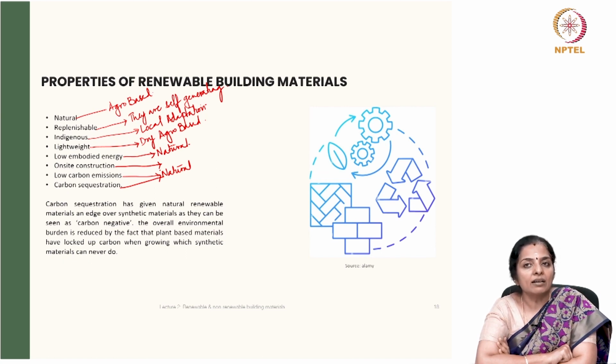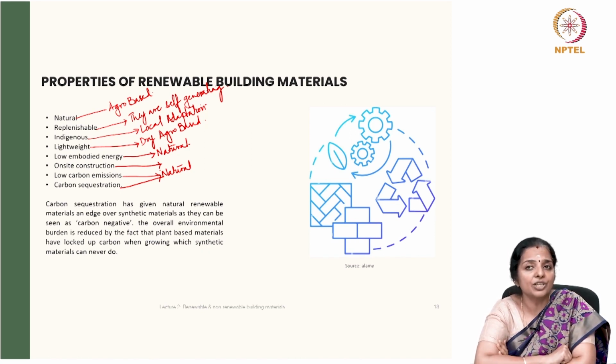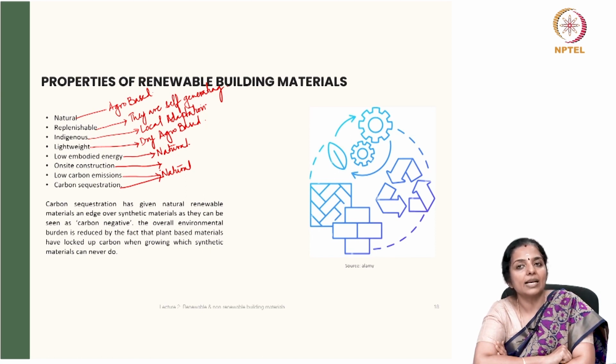Studies on the embodied energy consumption in buildings which have been carried out by UNCHS in the year 1991 have indicated that a high proportion of the energy used, almost up to 90%, is used in the production and transportation of building materials before they are brought to site. Only 10 to 20% of the energy used takes place in the on-site construction process. Thus, renewable materials which are natural have less embodied energy.